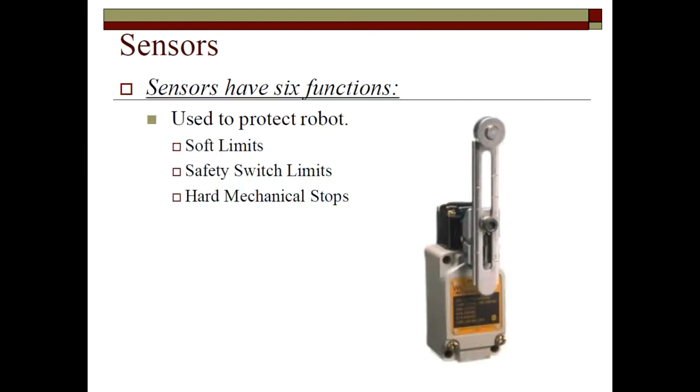All right, but other types of sensors, a lot of times we have the choice to wire them normally closed or normally open, depending on how we want it to behave. Now, the other side of that, I'll show you later on when I pull up the RoboGuide software, is let's say that you wired this particular sensor as a normally closed, so it's always putting out a 1 when there's nothing there, and then when something comes, it goes to 0, and that's backwards for you.